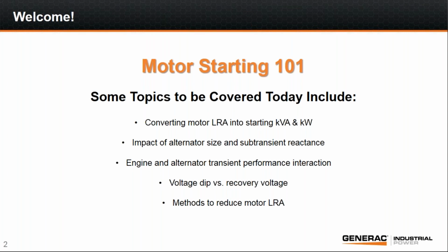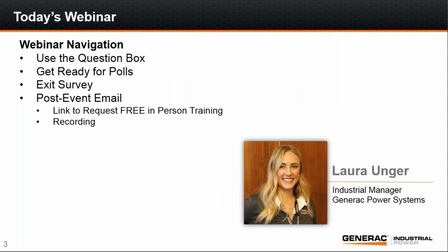So some topics we're going to cover today include converting motor LRA into starting kVA and kW, impact of alternator size and subtransient reactance, engine and alternator transient performance interaction, voltage dip versus recovery voltage, and methods to reduce motor LRA.